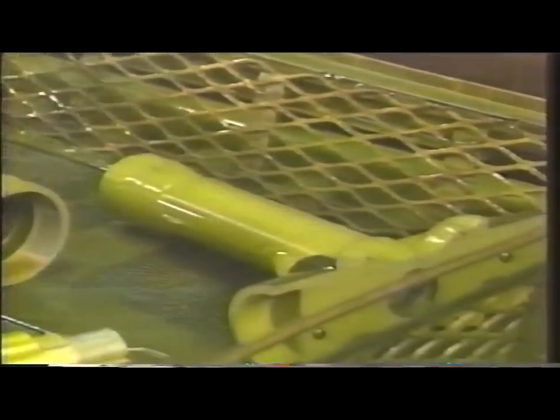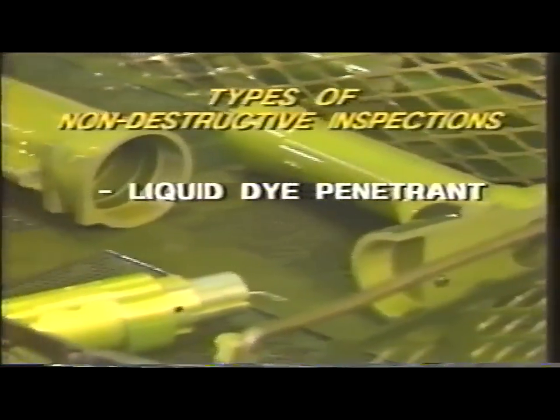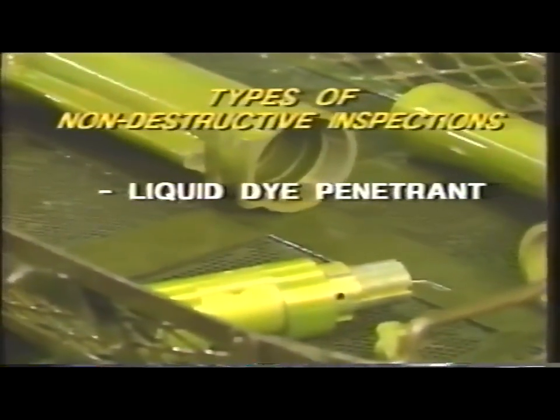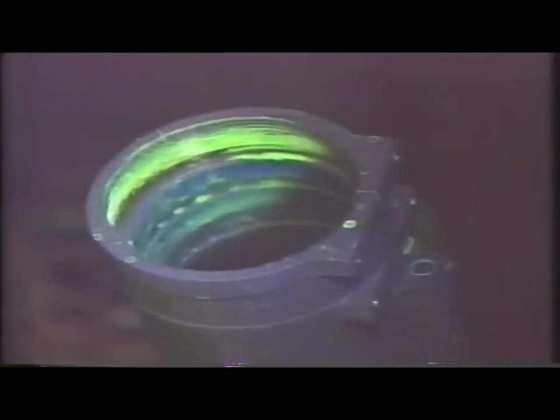The remaining NDI methods are only performed by qualified and certified NDI personnel. Each method has limitations and requires properly calibrated equipment. The liquid dye penetrant process can locate large stress corrosion or corrosion fatigue cracks on non-porous ferrous or non-ferrous metals. Dye is applied to the metal and enters the cracks. The dye is wiped off, and a developer is applied to the part which draws the dye to the surface. The area is then analyzed under a black light.